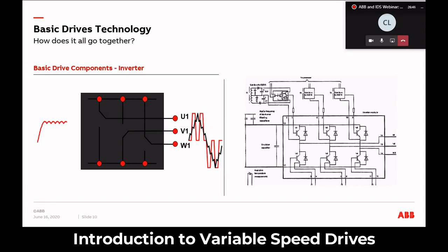And it's typically the longer the length of the cables, the motor cables per se, we then have to put extra measures in there to make sure that we get a more pure sine wave signal, so that we don't cause any significant damage to the motor insulation and the motor itself to break down.